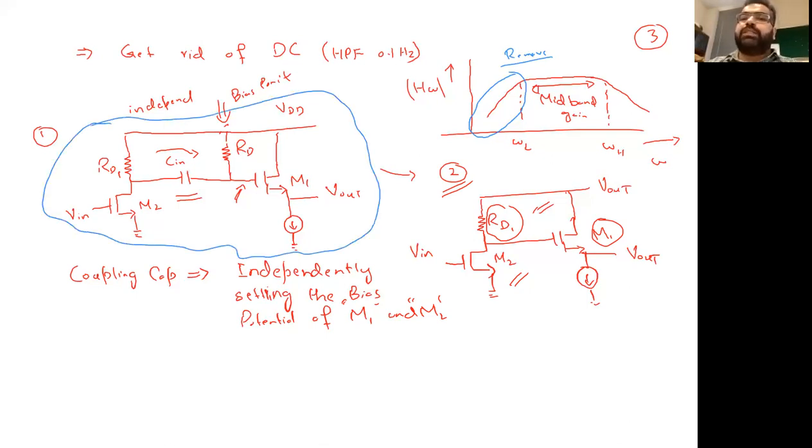So the capacitance is needed for multiple reasons. First, we want isolation, not only in terms of operation but isolation in terms of selecting the value, so that we can operate at an optimal position. Whatever value we want, we can set it for ID in this configuration and use it. And second, we also want to remove the DC values. For both of these configurations, we need to have an independent selection. If you have any concern or comment, just let us know, so we can try to clarify your confusion.